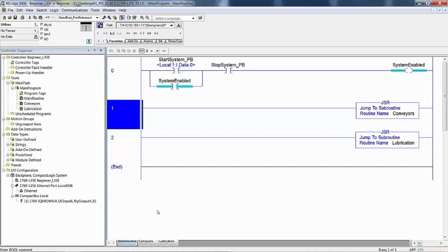If you know the surface speed of your conveyor, and you know the length of the conveyor, then you can create logic that determines, once it sees the leading edge of the carton, after a certain length of time, the leading edge is going to be at a certain distance from the entrance based on the speed of the conveyor belt and the elapsed time. Just something for you to think about. When you get done with this manual, you could go in and play around with that.